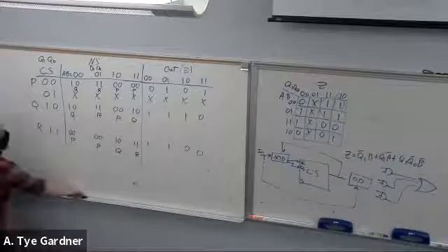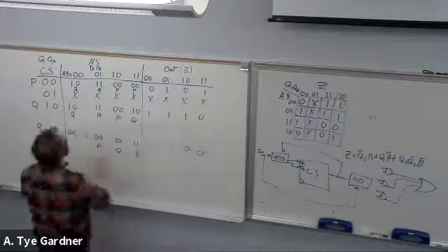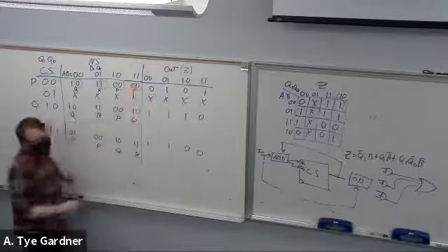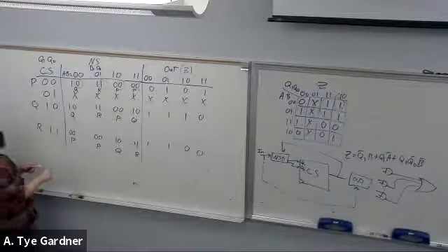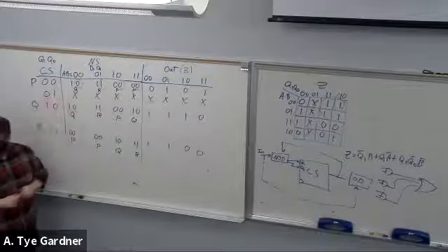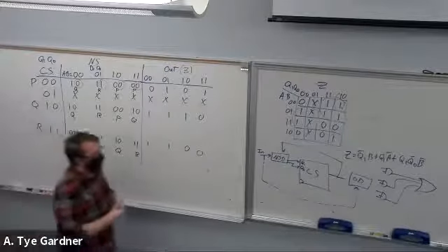So the first time I go ahead and look at the first bit of my next state decoder. And then I'll do the second bit, right? Do the LSB, then the MSB. I pick one bit at a time to write the K-maps for.